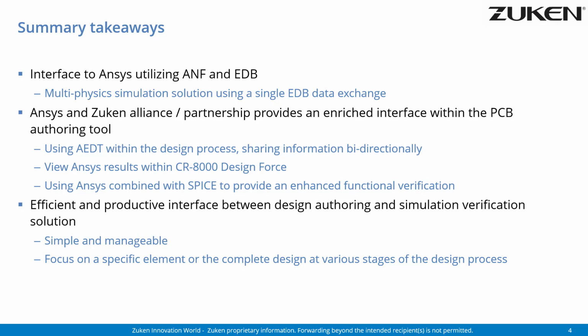Also, using SI Wave, for example, we can display the results for the DC volt drop or the frequency sweep directly inside of Design Force. Once we have a physical layout, information from SI Wave can generate the parasitic element models for the tracks on the PCB, and this can be added to the functional verification performed using SPICE from the circuit design aspect. These interfaces between CR-8000 and Ansys provide an efficient and productive design environment.